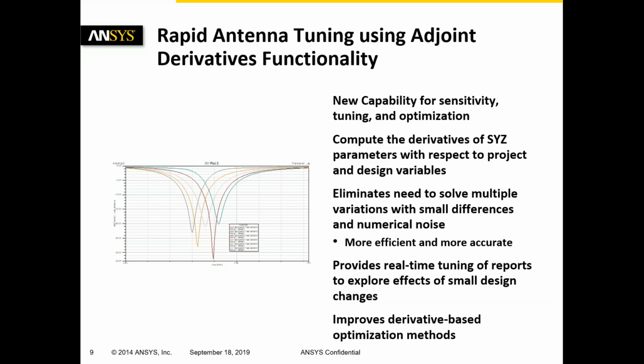What this means is that if you have a variation, say on the dimension of the antennas, you can tune the result plot by just playing with different scenarios of different variations. As you can see, the plot here, the different color represents a single entry, a single number for the variation on a dimension. So with the different design variables, the antenna performance results will vary.